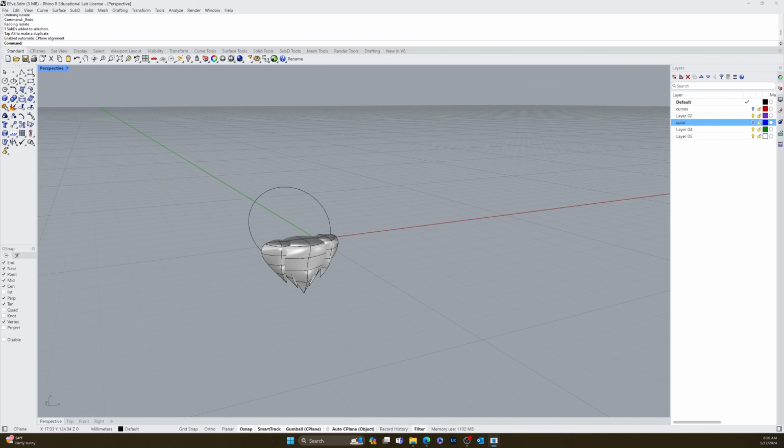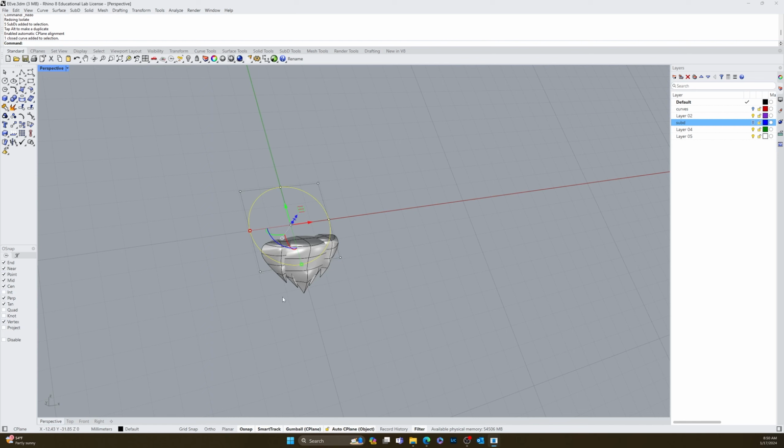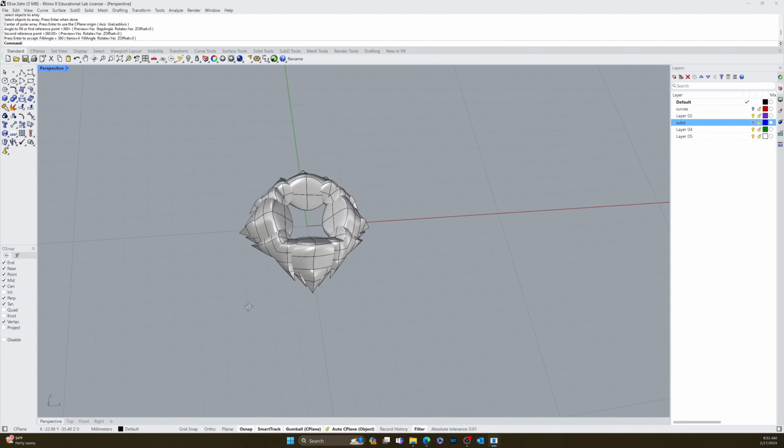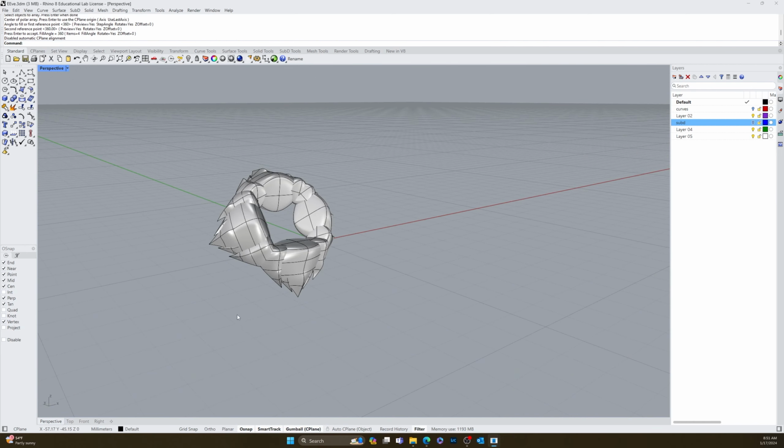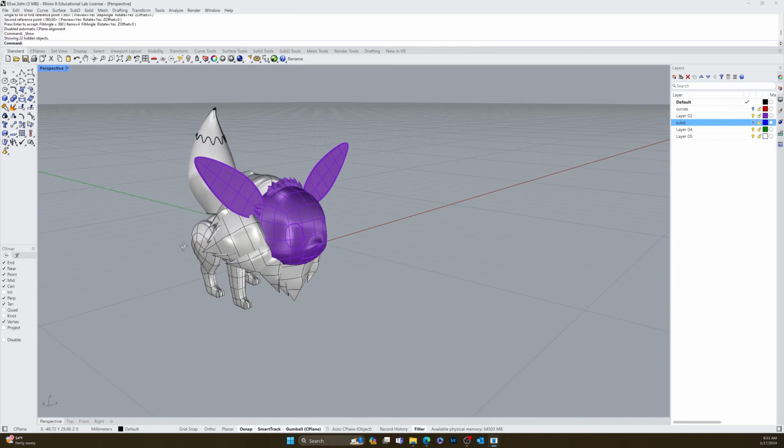Auto C-plane, click on this. Array polar. Select the object to escape because it's arraying the circle. Array polar, select the object, enter, select the center of our circle. Enter, and we have 4 already selected. So then we click, enter, enter. All right, cool. And then we turn off auto C-plane. And then we bring everything back.